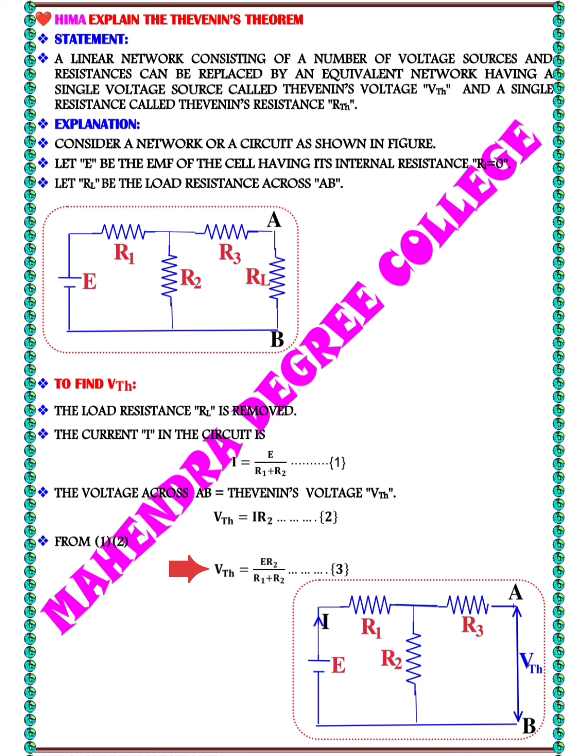The voltage divider rule is a way to calculate the voltage drop across a specific resistor in a series circuit. It's based on the principle that the voltage across a resistor is proportional to its resistance in the series circuit, where E is the source voltage, R1, R2 are the resistors in series. VTH is the voltage across resistor R2, simply Thevenin's voltage.